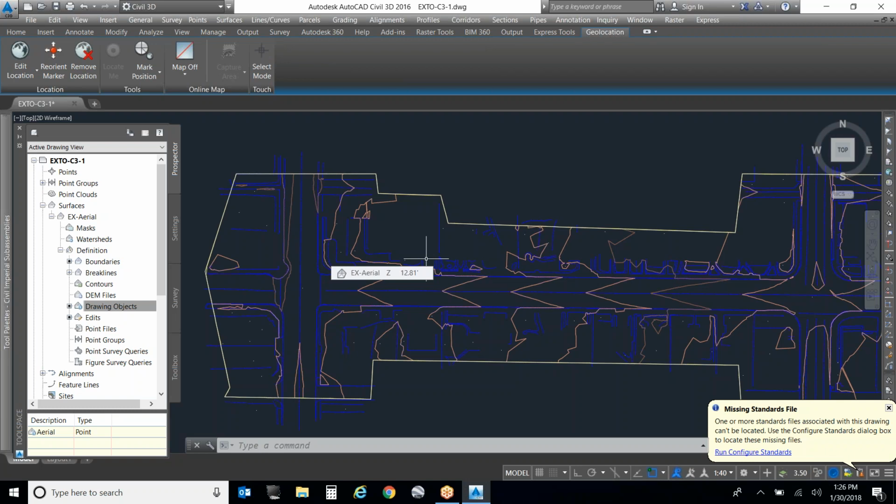They'll have that data in there with all the elevations. A lot of times if it's flat, they'll just give you a center elevation because basically all the inverts are the same, unless you told them to get more accurate information. If you wanted something down to the 100th, but again, it's not down to the 100th if the level circuit is at 200ths. So keep that in mind.